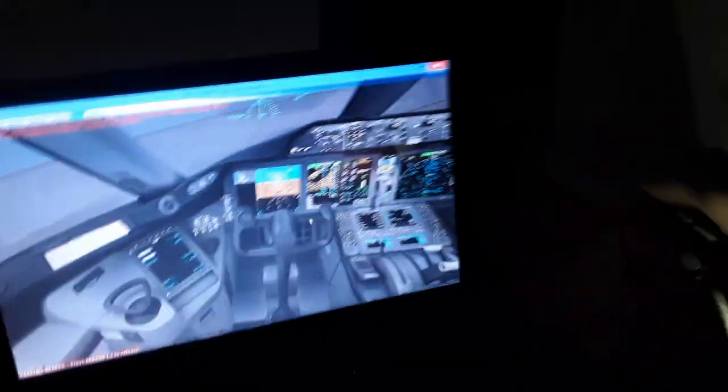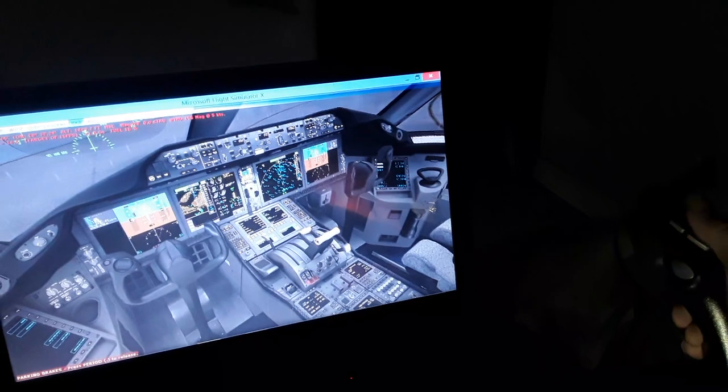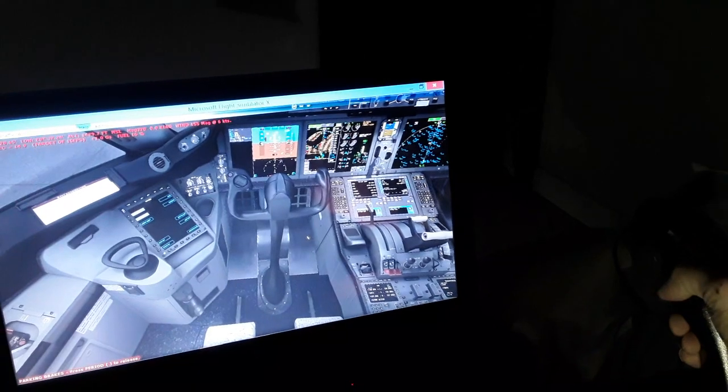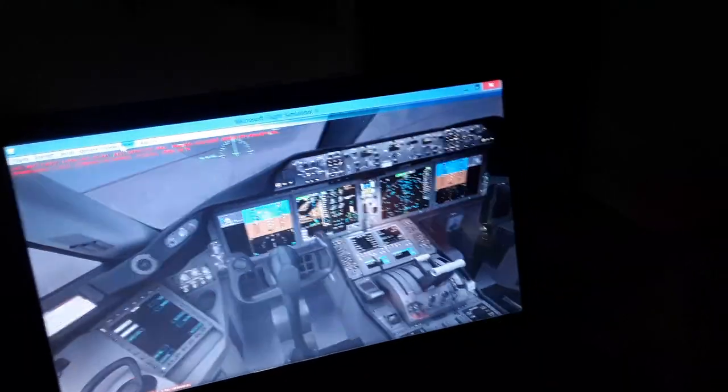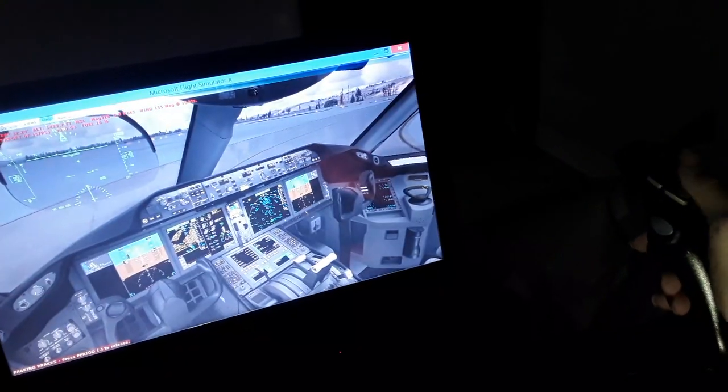We have also the rudder pedals for the yawing turns, the rudder. Also in the rudder pedals we have the nose wheel steering on the ground and the toe brakes. So you can see the nose wheel steering also. We have the tiller and the rudder pedals, so they are interconnected from 0 to about 76 knots. The deflection of the nose wheel from the tiller decreases from 76 degrees to about 7 degrees at about 45 knots at takeoff. Then it decreases to 0 at about 70 knots. Then you have only the rudder pedals.